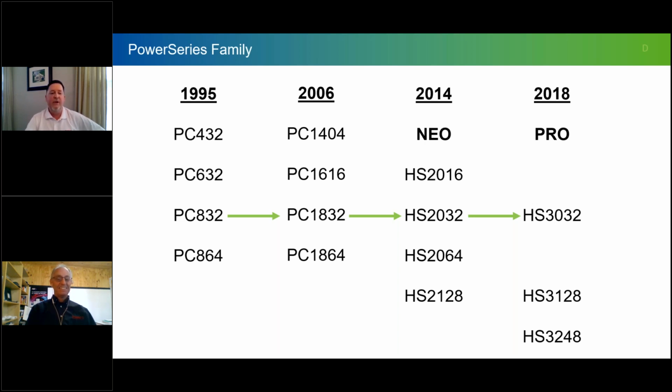If we go back into history a little bit to the 832, 26 years ago now, where did you program your zone definitions for zones 1 through 8? 001. Same as the Pro. How about line supervision for the panel? Single end, double end, normally closed. Section 013. Same as the Pro.